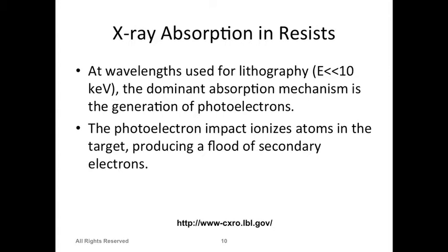So yeah, secondary electrons are important in lithography, but on the other hand, if you have too many secondary electrons, then it will be harder to actually control the exposure. And if the X-rays are too penetrating, which is also not good, then your material will be very, very sensitive to the X-ray.